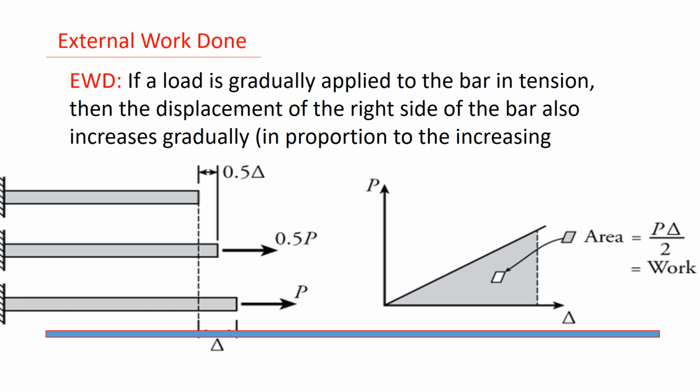In any closed system, energy can never be created or destroyed. We just have to recall conservation of energy from physics. Since work is a type of energy, any external work energy that is applied must go somewhere in a structural system that is deformed slowly. The external work energy is typically converted to strain energy in the structural members.